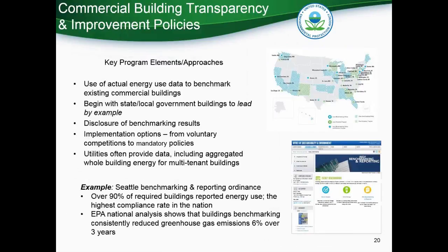I'm going to just interject real quick because, given the breadth of the audience here, we're trying to make sure everybody understands the language that we're using. So Tracy used the word retro-commissioning. And the way to think about that is going back into a building and looking at the operation of the existing equipment and fine-tuning and making sure that it is really working to deliver the savings that are potentially there.